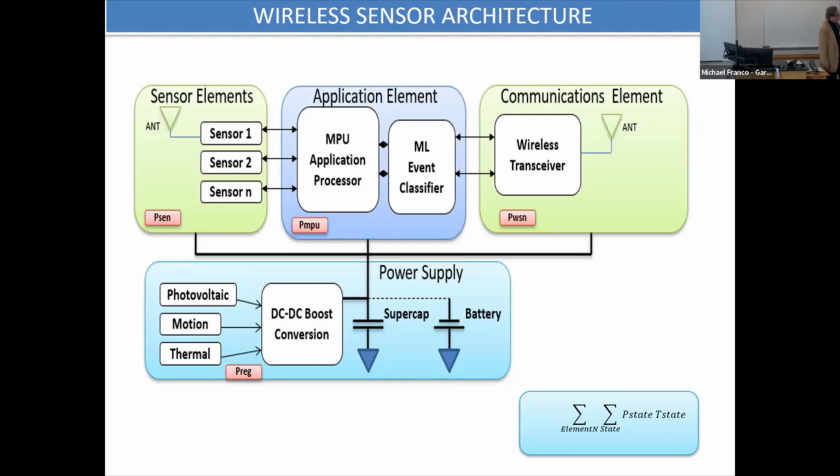At the same time, there's been a constant drive to take power out of your applications processor. The latest Cortex SAM series, for example, works in microamps. There are ways of dialing back the power by dialing your clock frequency, your duration, your duty cycle, and so forth. And the newest generation of MEMS sensors, accelerometers from Analog Devices, is down to 23 microamps working. So it works down very, very low.